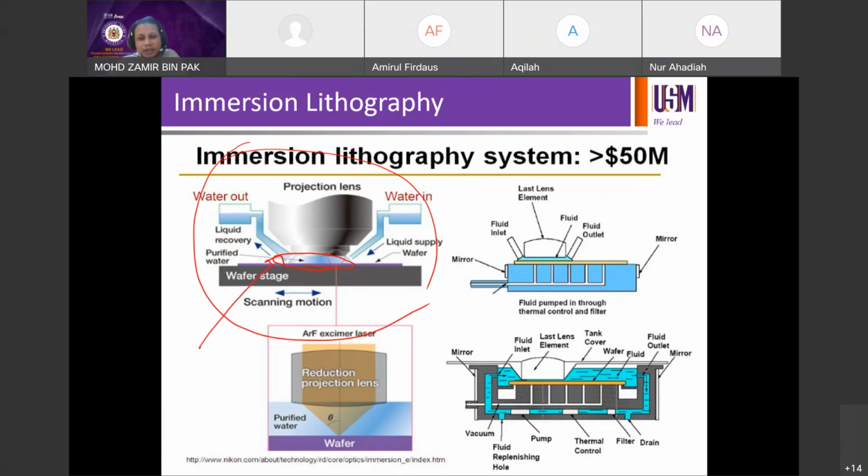In this case, we call it immersion lithography. It means lithography in water. We use water for the optical process. See, the projection lens here, then purified water is used in between, the wafer sits below, and your resist is down here. So in between there's DI water, DIW. Why immersion lithography? It's not for cooling because it's not hot. It's for optics. Reflection purpose?